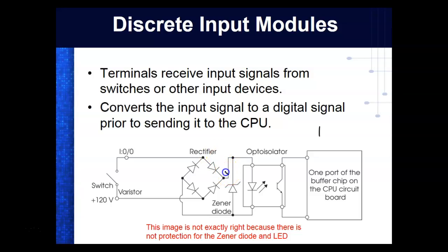We would have to have a resistor right here. So what this guy right here, this is a rectifier. What did I tell you rectifiers do? Converts AC into DC. You take solid state, you'll learn about that. Then this is what we call a zener. This is a voltage regulator. So what it might do is it might clip this and make it 24 volts, no matter what we get in. But you got to have a resistor in there.